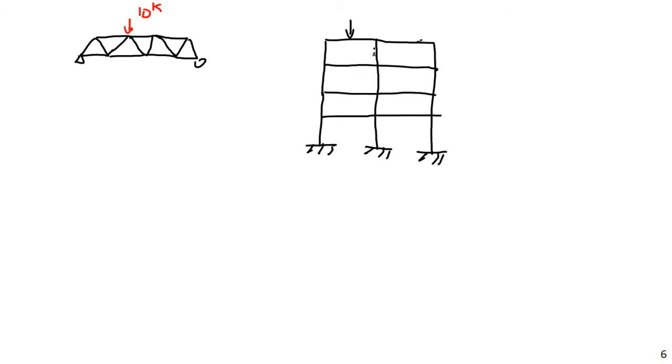It's not going to immediately cause global failure of the structure, because if there is enough stiffness in here and in this column here, and this one can't take the required load, it is possible that this one over here and this beam over here may be able to distribute that load to other structural elements. Again, statically indeterminate systems fundamentally represent redundancy. Often this can also lead to efficiency.